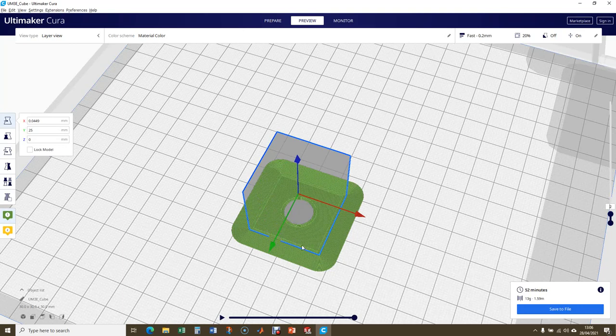And it does that for strength. So if we just continuously printed in the same direction, you wouldn't get good adhesion between layers. They'd be weak. So this makes it very difficult to snap even a thin sheet of this material. So like plywood, it's keeping the grain alternating up and down. So that's the lines. As we go up, the lines alternate 90 degrees every time.